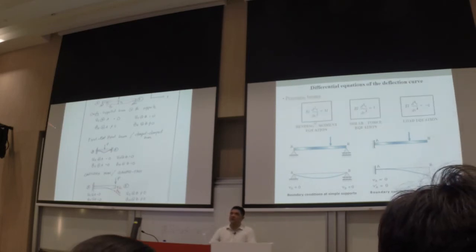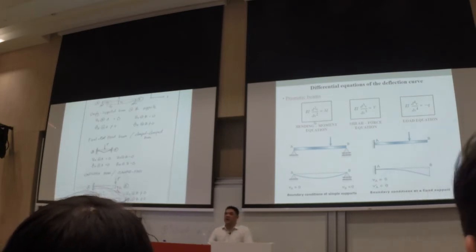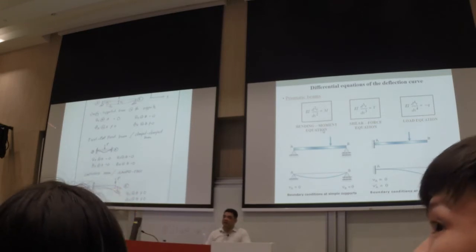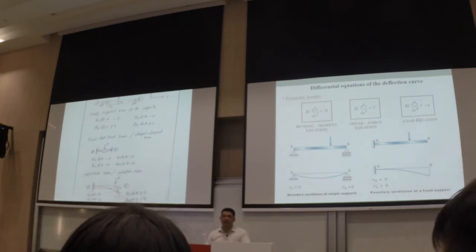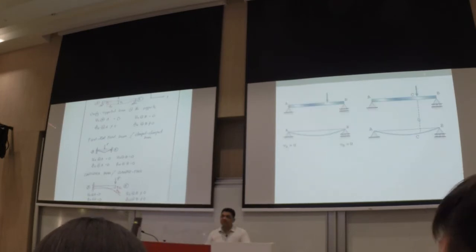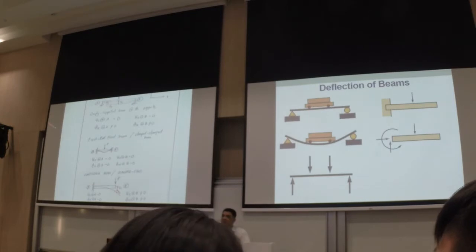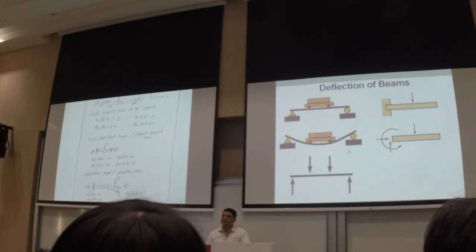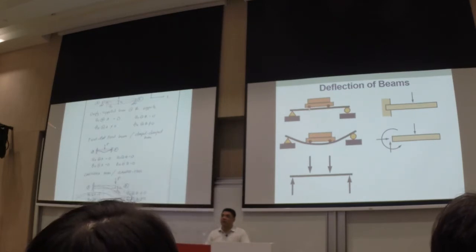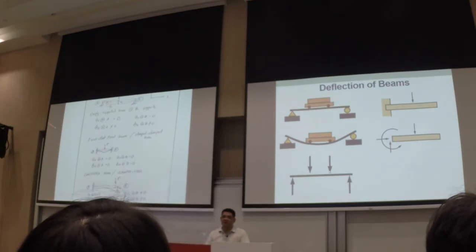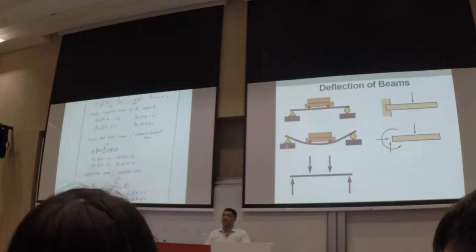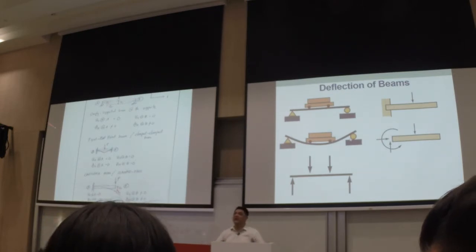So here we go. We have the bending moment equation. So after knowing the boundary conditions, we're going to look at the bending moment, the shear forces, as well as the loads. Okay, so this is how we study beams. We have a loading and there will be deflection. So here, probably we can represent this one as something like this, where we have a load there at the wheels, and then we have forces or reaction forces at the supports.